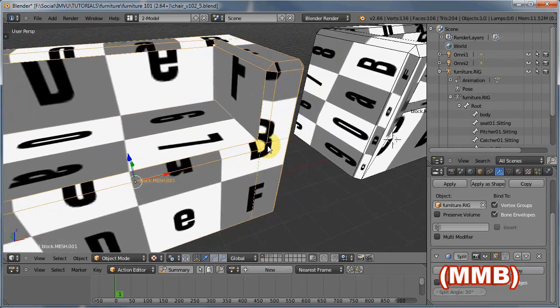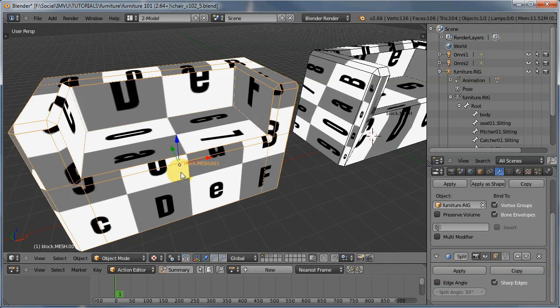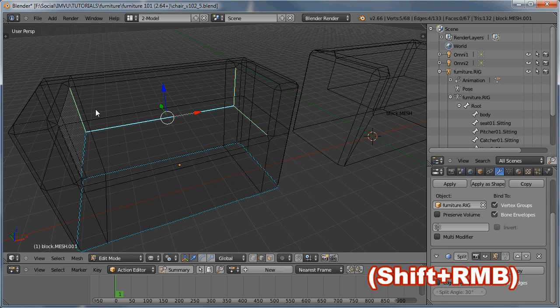Now ordinarily, as we did in the first chapter of this workshop, we selected a group of surfaces and mapped them to the texture. That's not a very efficient way to unwrap a relatively complex shape. A better approach is to use something called seams, and this involves basically just going around the mesh, selecting edges and marking them as UV seams.